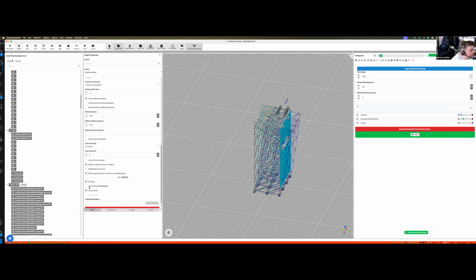And this can be for everything. So this use in second wind speed applies to wind load planes. This applies to all the other parts that you have in here, so that you really can level what kind of calculation goes into here and have two wind speeds in here. So one in use with all the LED walls up and one out of use with the LED walls down mounted with this. So that is the advantage of this.